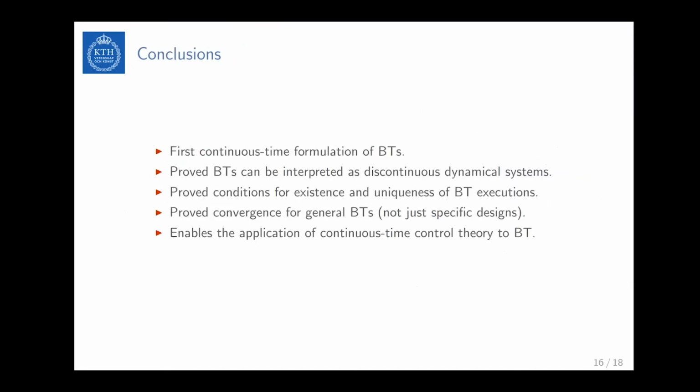So just to reiterate the conclusions, it's the first continuous time formulation of behavior trees in the form of discontinuous dynamical systems. And we proved existence and uniqueness of the solutions of these discontinuous dynamical systems. We also proved convergence for general behavior trees, not just specific designs. There have been some papers before that proved convergence for specific behavior tree designs, but the theorem that we present here actually proves it for general ones. So it can apply to any design.